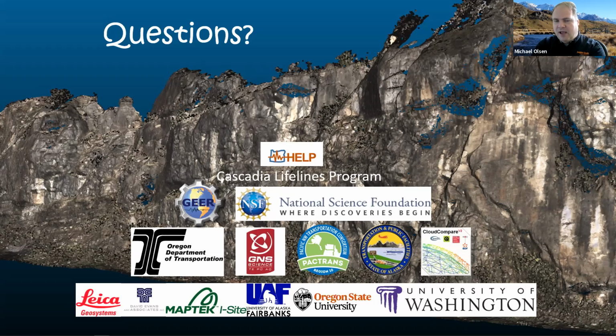We also have our other sites in Alaska that we've been studying for years. There was recently the Anchorage, Alaska earthquake in November 2018, and we've got a really good baseline set of scans before, and we've also done some scans after. One of the challenges with Anchorage is our sites are in areas where the peak ground acceleration was about 0.1 to 0.15, where you don't quite see as much of these effects. It needs to get up to about 0.2 g or higher to see those longer term time decay effects. But definitely, we're interested in seeing these trends and how they hold up across the globe.